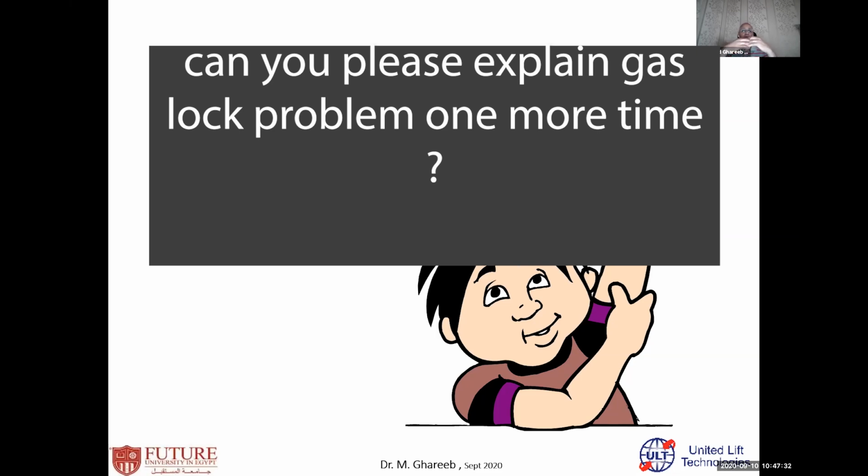New fluids coming from formation. In the downstroke, my traveling valve should be open and displace this fluid. But if I have a gas lock, what will happen inside? Gas lock means the two valves close. It does not allow the two valves to open.